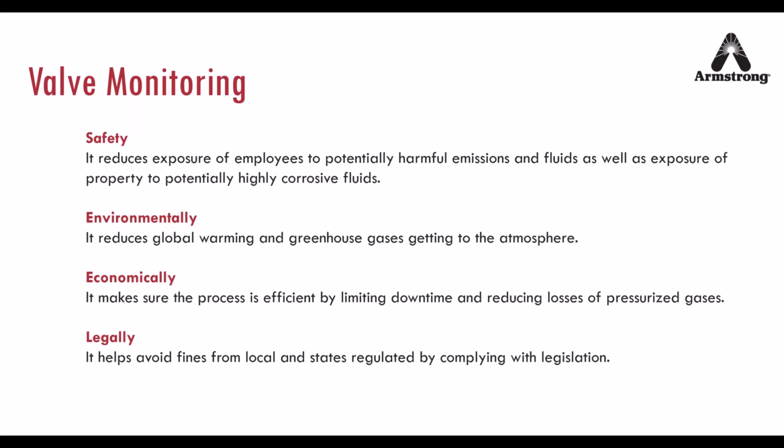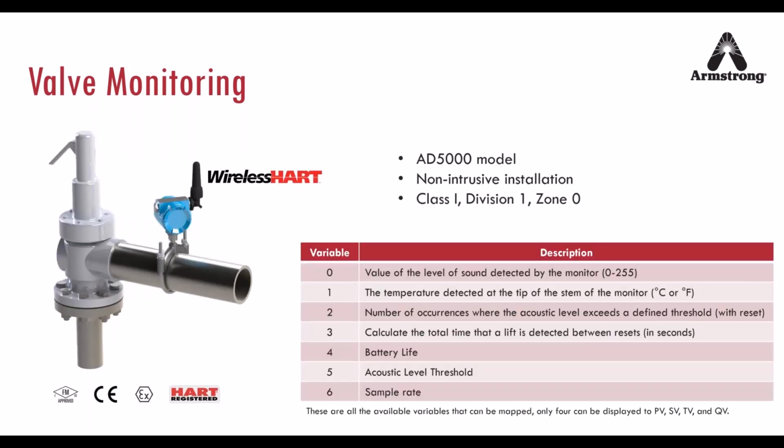So that's why Armstrong also developed a WirelessHART device which is specifically for valves. In this case, it's a safety relief valve, but we do all kinds of valves: bypass valve, blowdown valve, stop valve, you name it. Anything you need to monitor, if it's open or closed, we can monitor that with the acoustic.